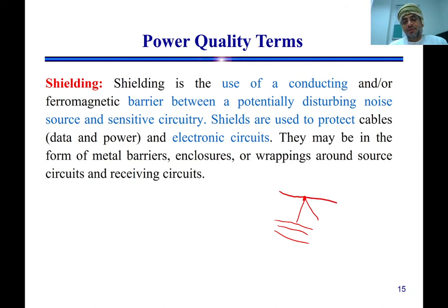that is running on the top, and we said that the purpose of this wire is to shield the structure. So in case there is lightning, the lightning will not hit the overhead line or the tower, it will hit this shielding wire, and of course the shielding wire is connected to the ground. Then that shielding will protect the insulator, the tower, and the different phases.